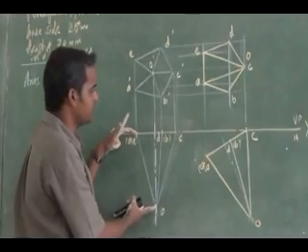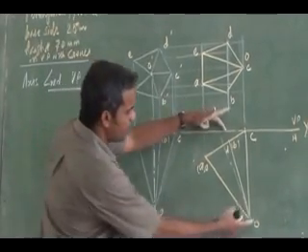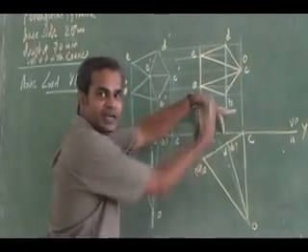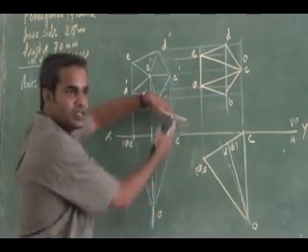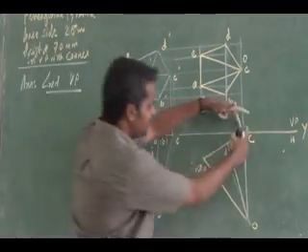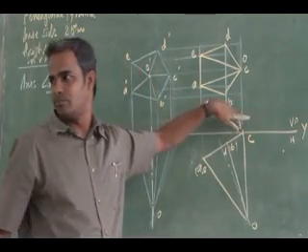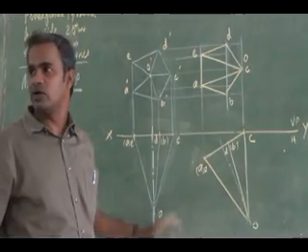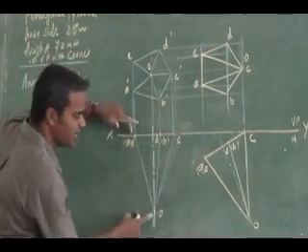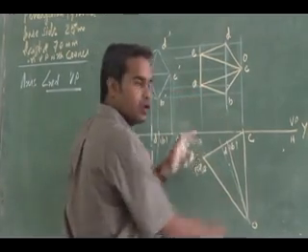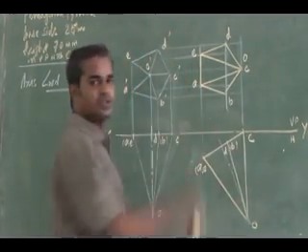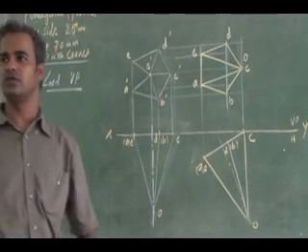That triangular face I have to mark and make vertical. If it is a slant edge, I have to mark CO. CO is nothing but an edge, and that edge I have made vertical. The same problem with a triangular face vertical means you have to measure AEO and show it as vertical. You have to redraw the top view and proceed for the final front view. Is it clear?